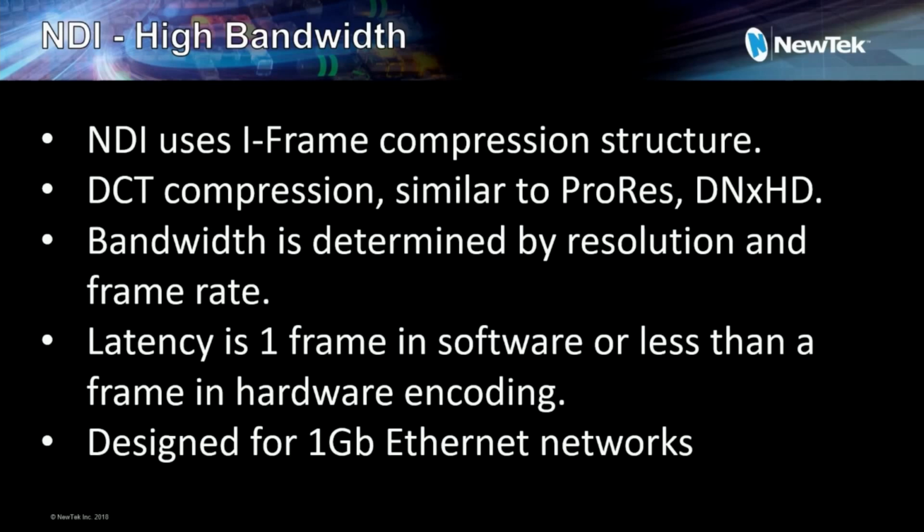Because this is I-frame only, we can get compression down to a frame or less. In software applications, it's typically a frame. It depends if we're talking fields or frames. If we're talking fields, it actually works at fields. In hardware encoding, we can do it in less than a frame. We can actually start compressing at lines of resolution. So we've got converter boxes out there made by us and other companies like Magewell and BirdDog, where you can show an SDI and an NDI connection between devices, and it's the same frame of video showing up on the other end.